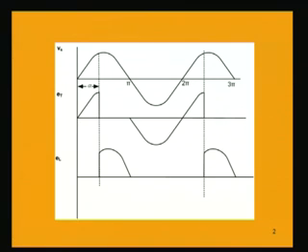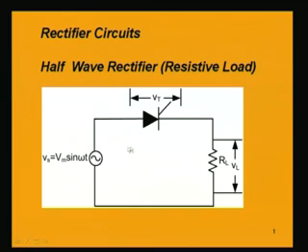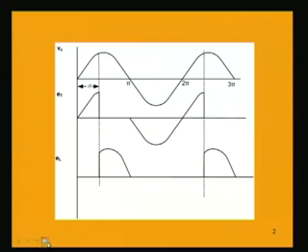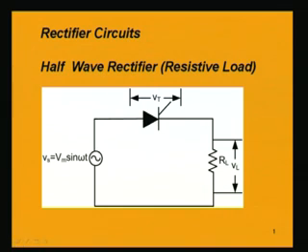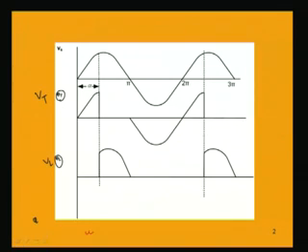So, the voltage across the thyristor will be equal to the input voltage, because we can see in this circuit the voltage across this thyristor, when it is not conducting, there is no current flow. So, the voltage which is at the input will be equal to Vt. I am using the symbol Vt and Vl here. So, what will be Vt? Initially it will be equal to the Vs. As soon as it starts conducting, it becomes 0.